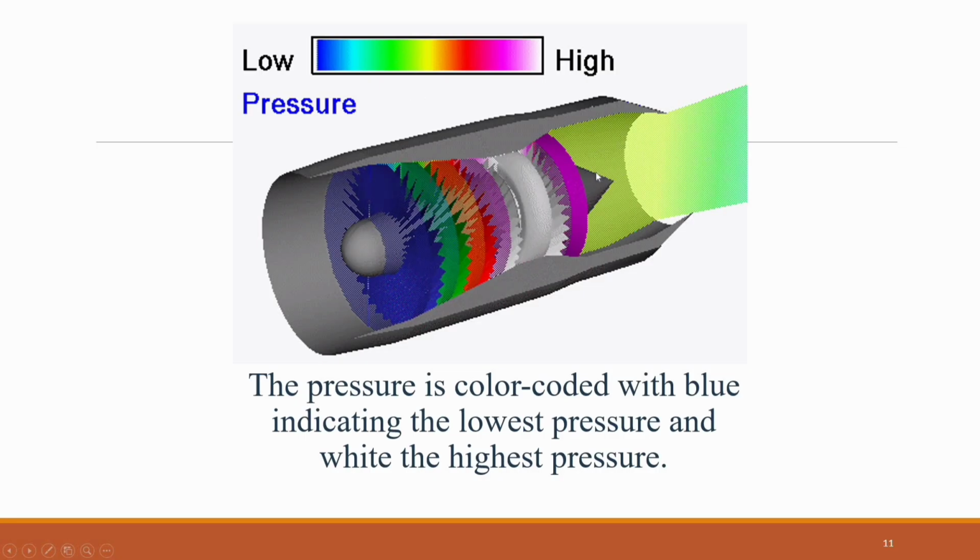Finally, the nozzle converts the remaining high pressure and temperature into high velocity. As the exhaust gases accelerate beyond the free-stream velocity, thrust is generated according to the turbojet thrust equation. This step-by-step variation in pressure, from the low-pressure air at the inlet to the high-pressure gases at the compressor exit, and finally to high-speed exhaust, illustrates the fundamental principle behind turbojet propulsion.